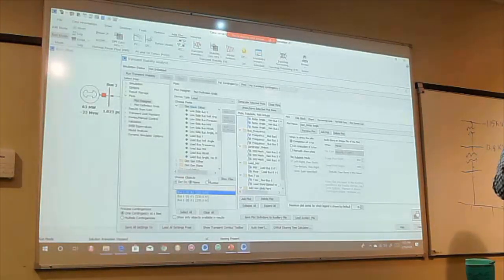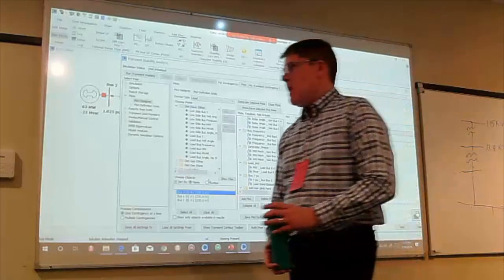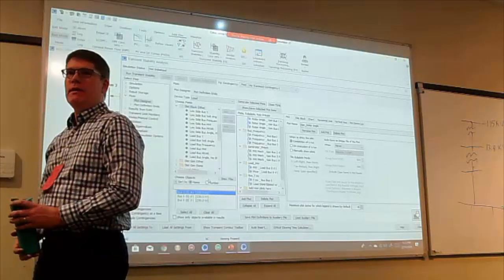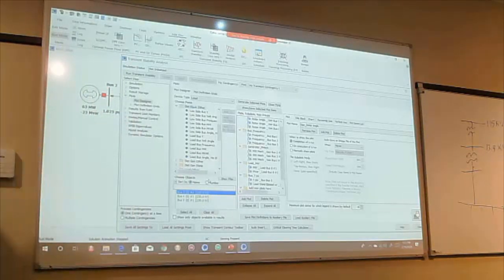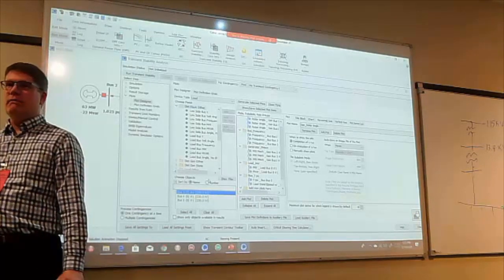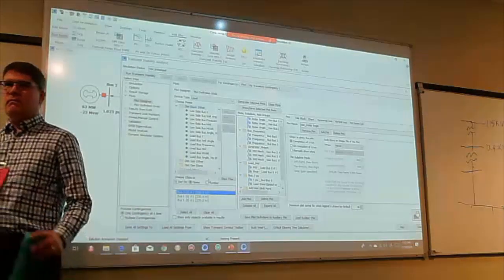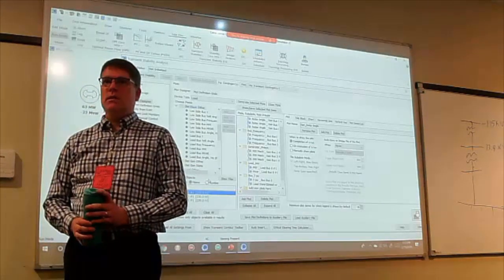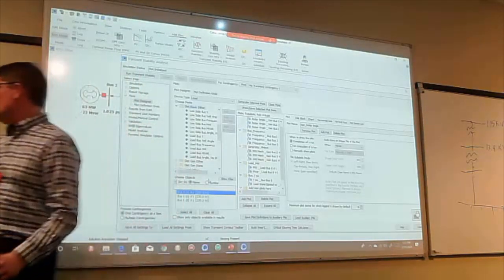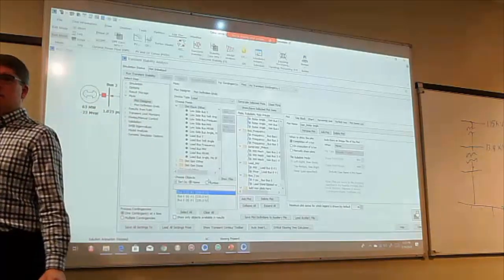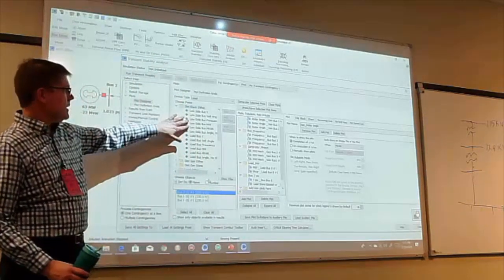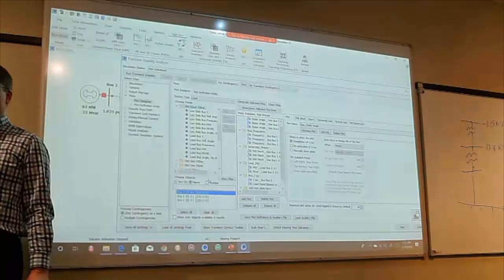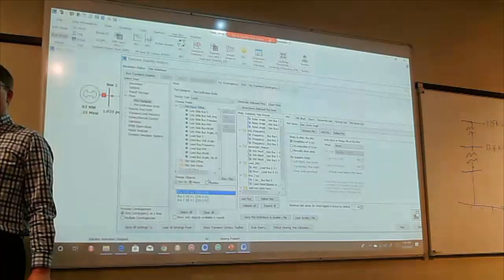Okay? Go ahead, Eric. Does it matter though? I mean, if you went really low, don't you get a lot more I? I guess it's all in per unit at this point. Oh. The impedances are normalized to per unit on this MVA base. Yeah. So it ends up not mattering. Okay. So you still might have a nominal I, or like a regular, yeah, I see what you mean. Yeah, I don't think we even let you know what the current is down here. I don't think that's in here. No, so we can tell you megawatt and megavar, but if you were to ask current down here, then you'd have to tell us what is the nominal voltage, and your answer would be, I don't know.